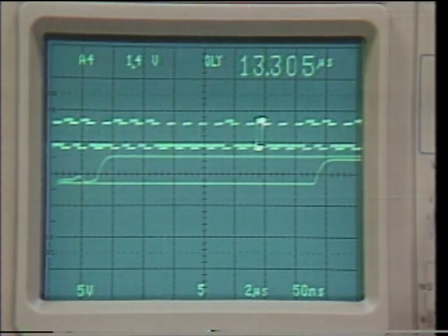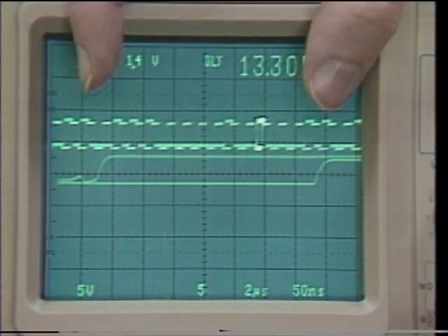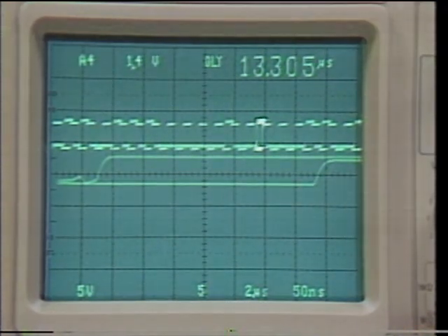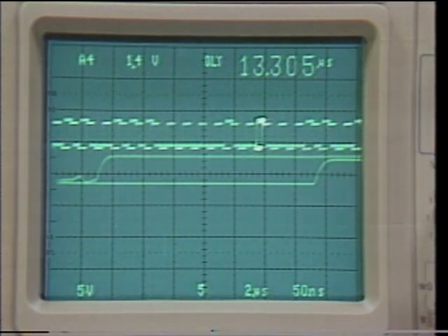Another reason for making measurements from the graticule rather than using a delta time, delayed sweep, or delta time cursors could be a single event that can only be observed in a photograph where there's no time to set up cursors or delayed sweep.